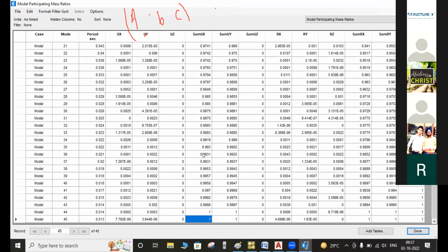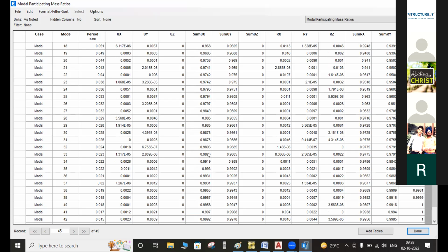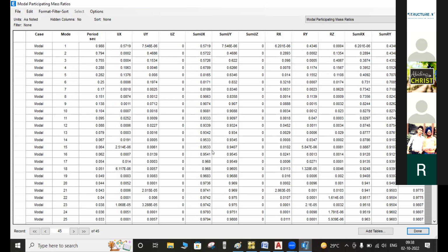So sir, once we check the ideal arrangements, mode 1, mode 2, and mode 3, then we see whether the mass participation crosses 90% or 95%, on the behalf of increasing the number of modes. It is the second check also. After that, the summation for the starting three modes should also cross 65%. So this type of checks we need to consider.